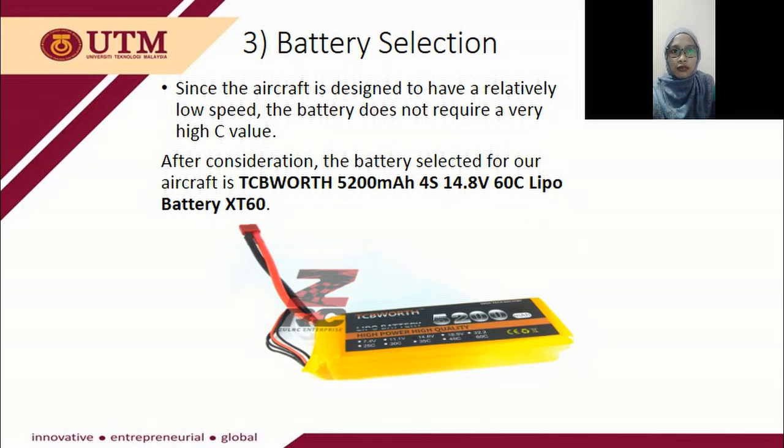After consideration, the battery selected for our aircraft is TCB, 5200 mAh per cell, 14.8 volt, 60C, 60 discharge rate, LiPo battery, XT60. This is the picture of our selected battery.